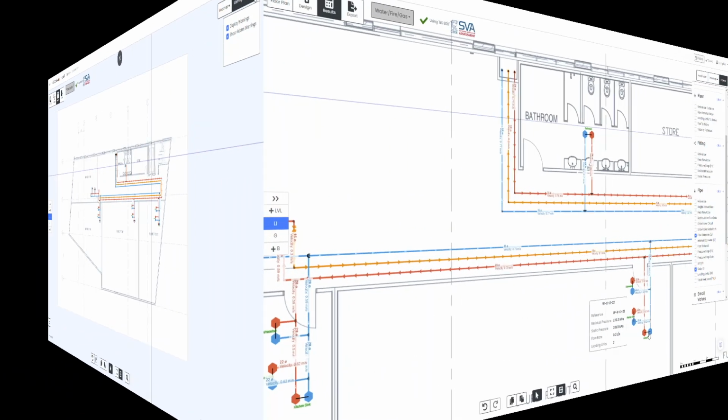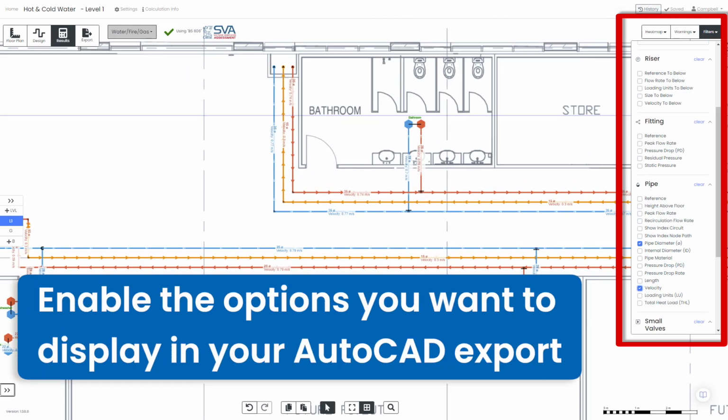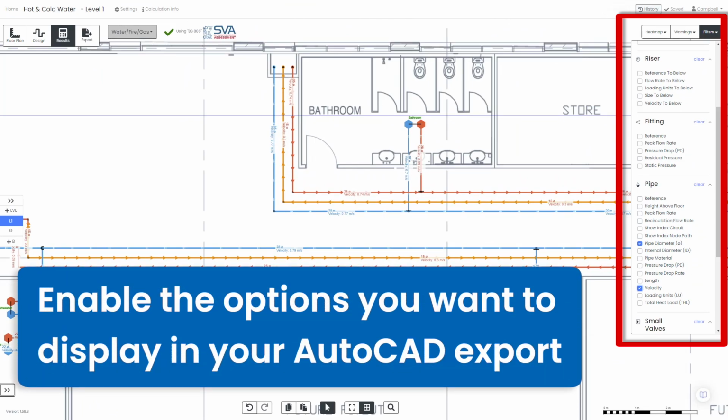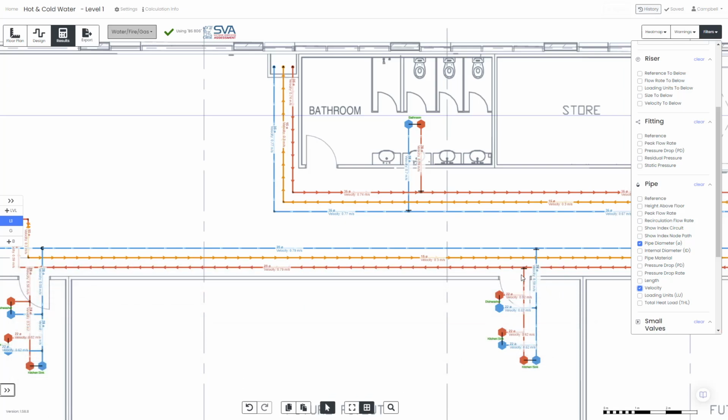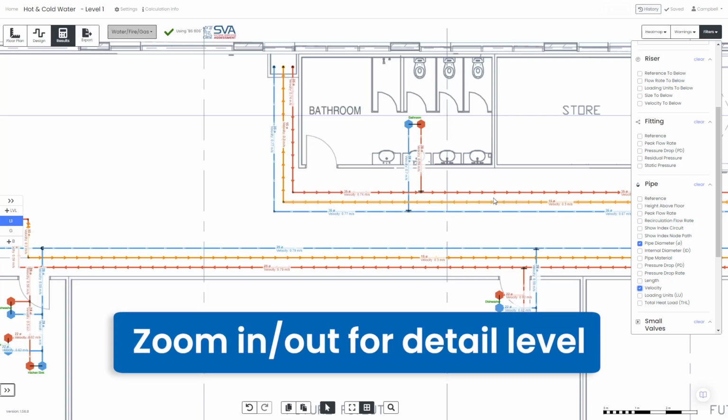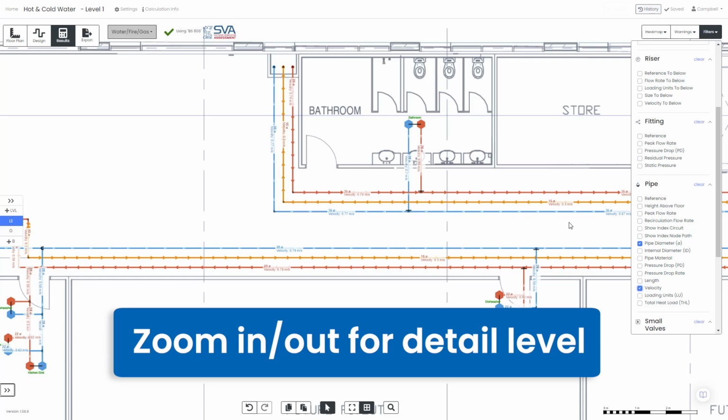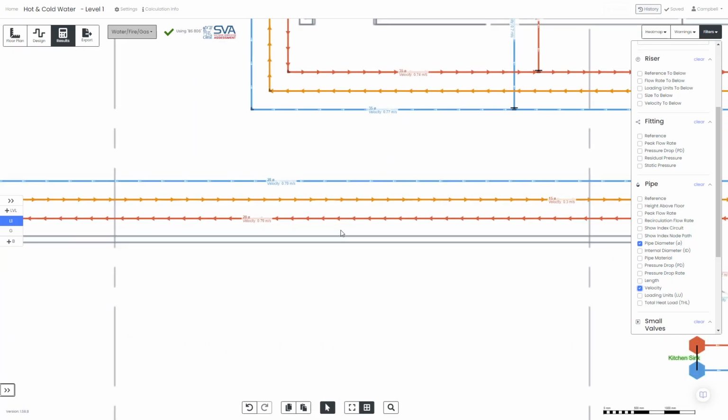Any result you select in this view will be shown on the export in the same location. Prior to hitting the export button, zoom in on a section of the drawing. Zooming in on an area with small pipe or duct runs will reveal the result for smaller lengths. Decide on the visibility you wish to export by zooming in to an area of concern. The closer you zoom here will impact the result shown on the export file.